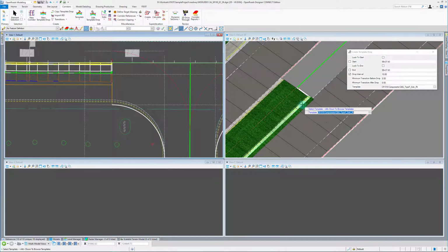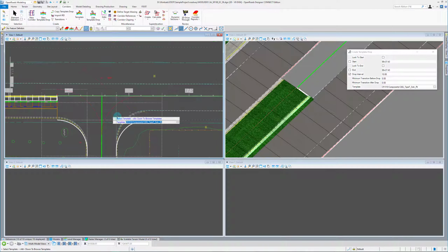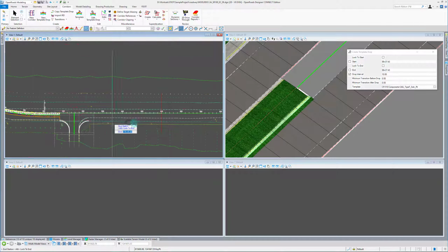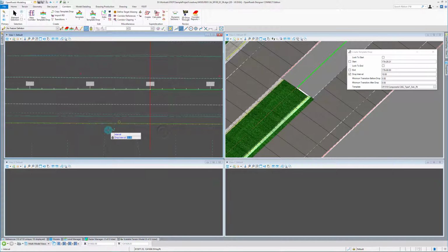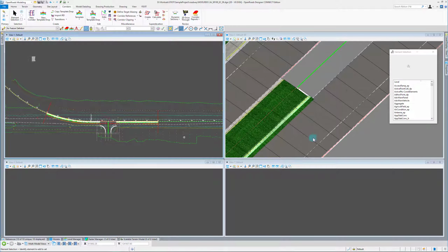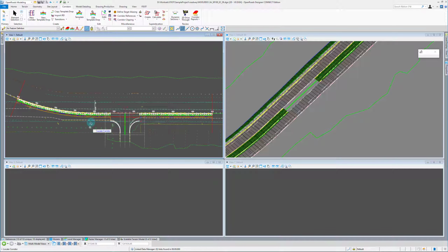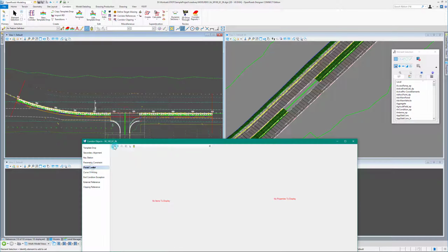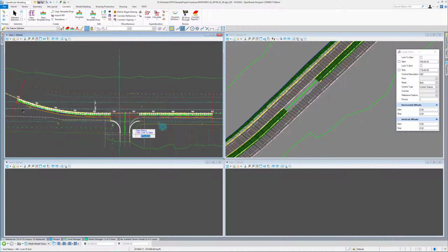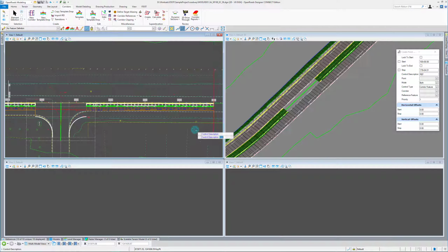And again, it's going to draw it in the middle like we did before, which is fine. So we're going to continue here. I'm going to do another template drop. Snap to here, snap to here. Click through. So because we've had our pavement run straight through here, we only need to set up one point control for this, which is basically the same exact point control we set up before. I'm going to do the entire limits. Call it ref again. Find ref again. You can see why ref is so helpful.